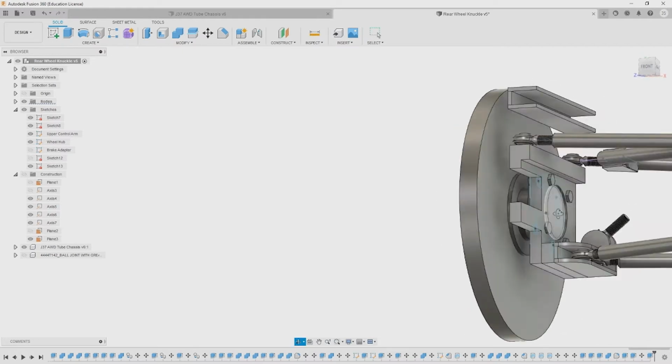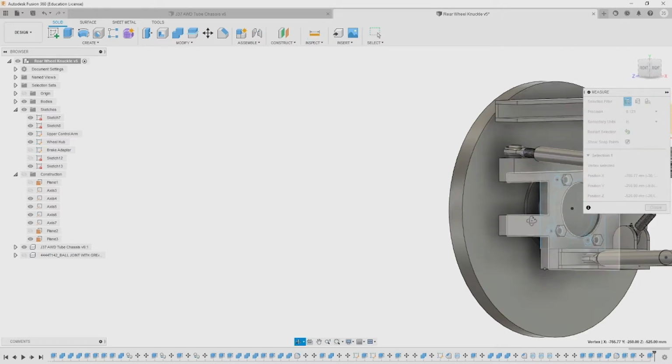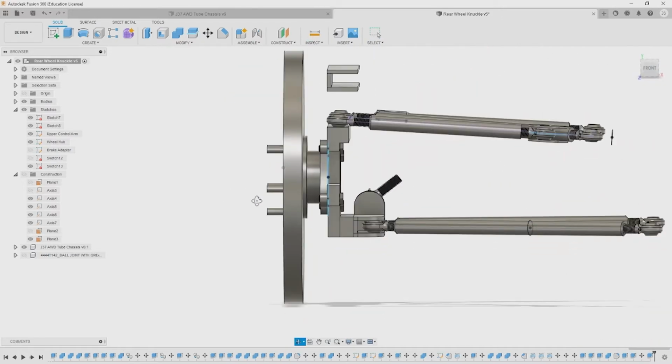But the bulk of the force is really going to be coming into that lower hub, and I think this top captive assembly is not going to be taking the kind of forces that the 2 lap welds are going to be suitable for.